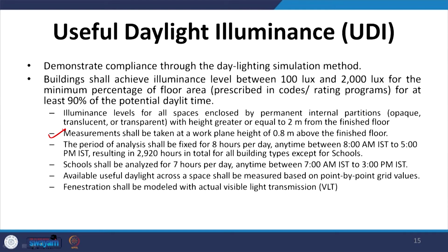If we are going ahead with the daylighting simulation method, we have to follow certain guidelines. First, the measurements should be taken at a work plane height of 0.8 meter above the finished floor, which is what we have already discussed.